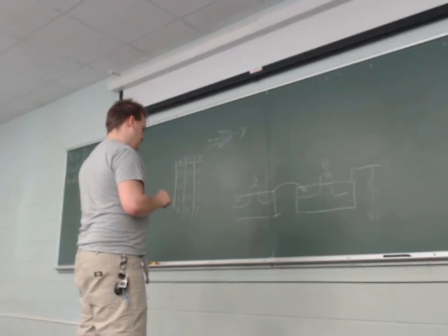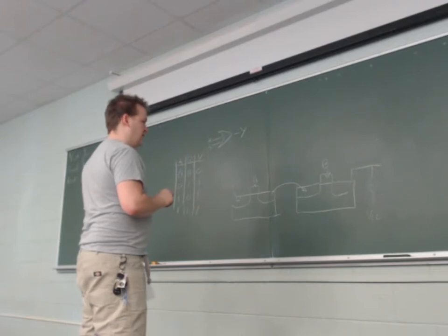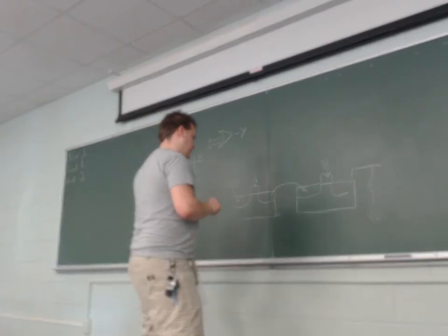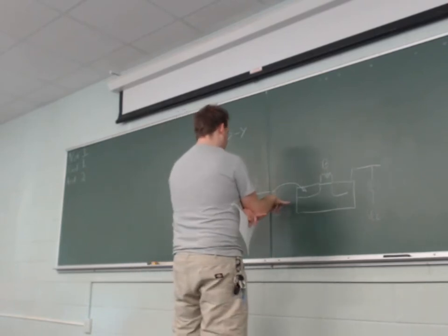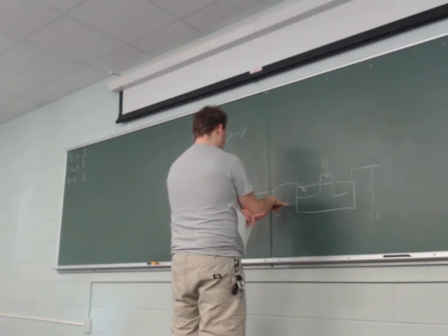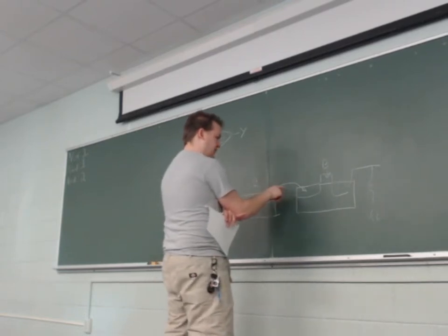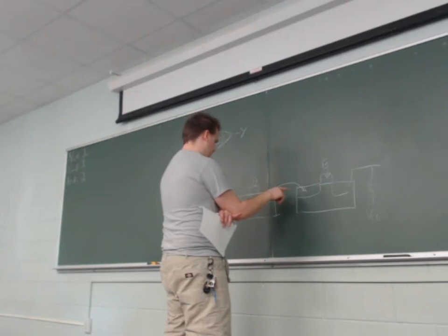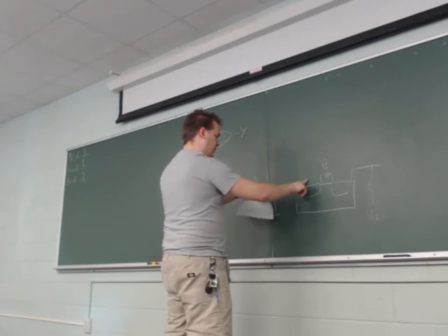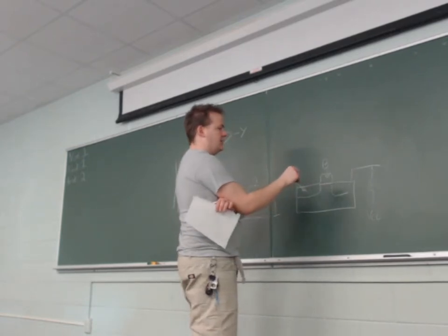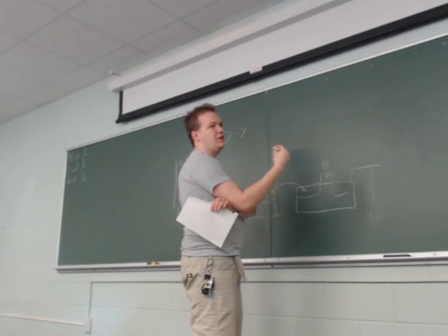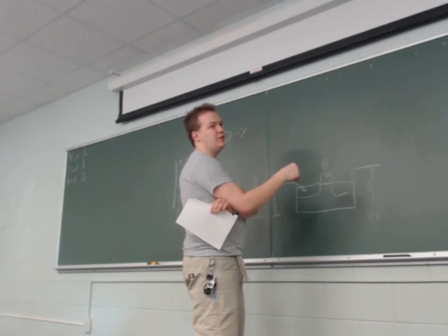Okay. So. These both need to be knotted. So the ground goes to. Hold on, I'm getting myself confused. Right here, you want to knot both of these, right? I'm trying to think. You mean A and B? I want A knot and B knot, so they're both knotted before they go into the NAND gate. That's gonna get you the OR.